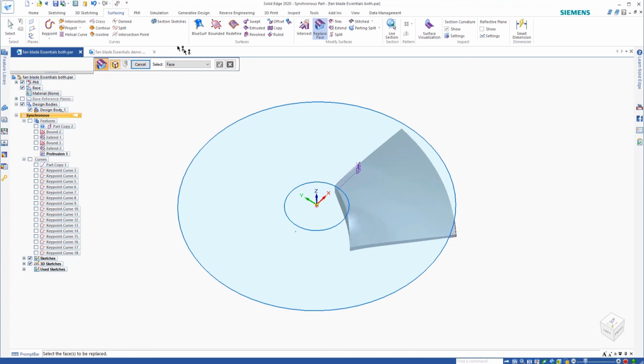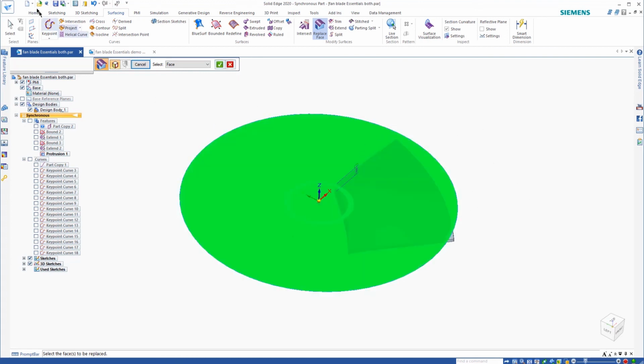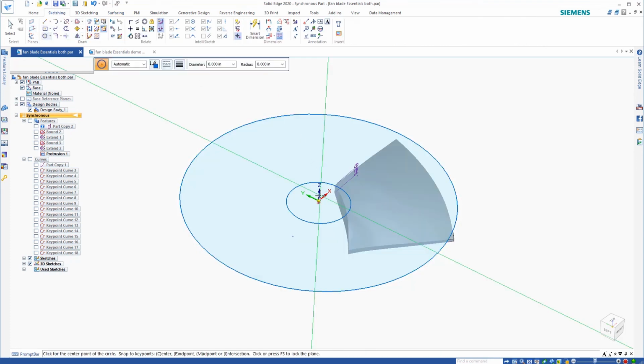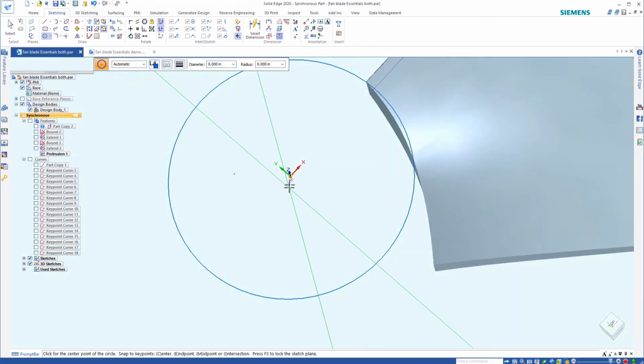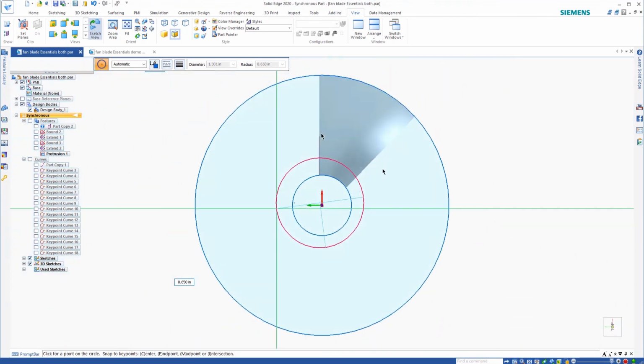So from here, there's a few different things you can do. You could go ahead and pattern this now if you want to, or we can go ahead and draw the center. So if I come over here and I click on this and go to sketching, we'll go ahead and select that plane there. And then let's go to view, sketch view again.